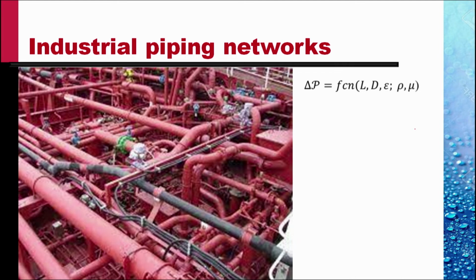The pressure that needs to be applied to a length of the pipe is a function of the length, the diameter of the pipe, the roughness of the walls, the density and viscosity of the fluid. Since we use pipes of various diameters and various materials and various thicknesses, do we do experiments on each different pipe to find out the pressure losses? No. The dimensional analysis comes to help.